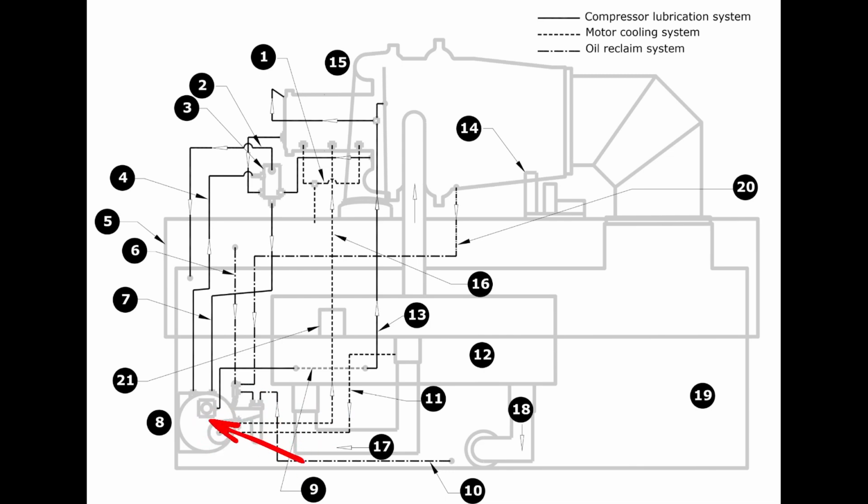our oil tank. Now, one of the other things we need to think about is if we're injecting refrigerant into here, and the refrigerant pressure coming into here is a medium pressure refrigerant, we need to get rid of that vapor. So all that vapor refrigerant that collects in here needs to go somewhere. It can't stay, and it can't stay trapped.